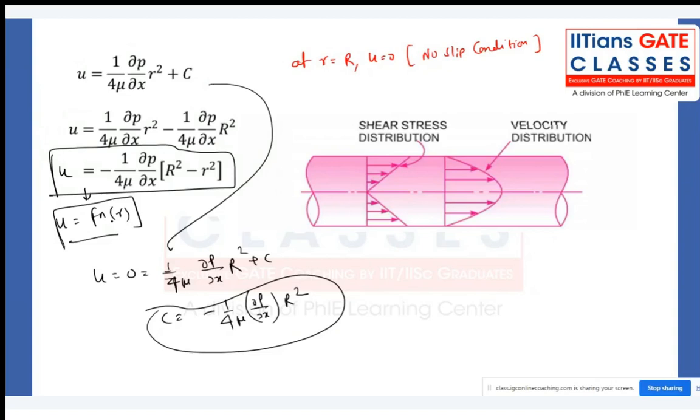Here we do not have a building height like 10 floors or 20 floors, right? So we don't need that. Only one pump is sufficient, that is the centrifugal pump. Even if your house or whatever roof where you have the tank is at a very high level, like a many-storey house, then what will happen? You need to install two pumps or three pumps in a particular what? Which combination? Series or parallel?